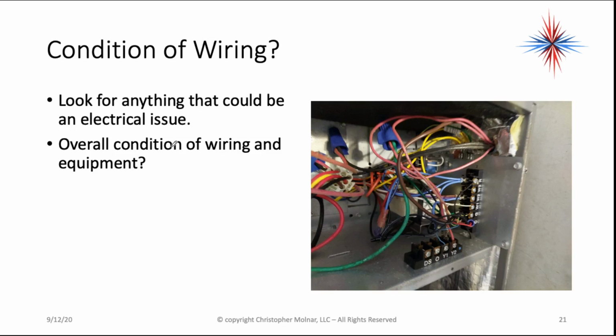What's the condition of the wiring? Do I have signs of moisture? Do I have electrical problems? Overall, the condition of the wiring tells me a lot about how the equipment was installed and maintained. In this case, it's relatively clean. I don't have any worries here.